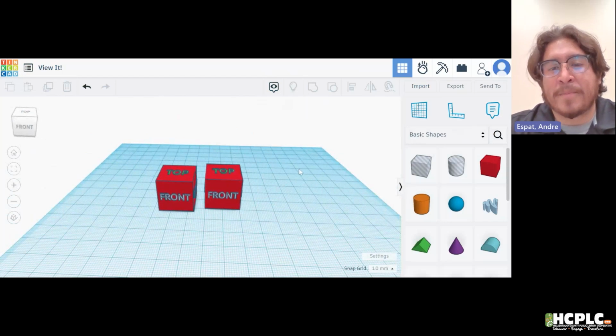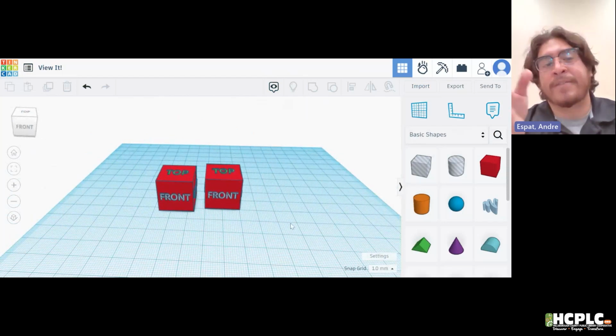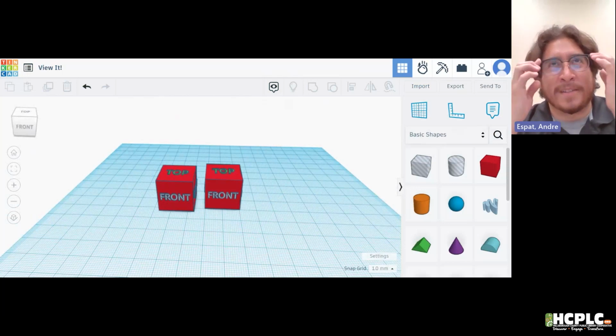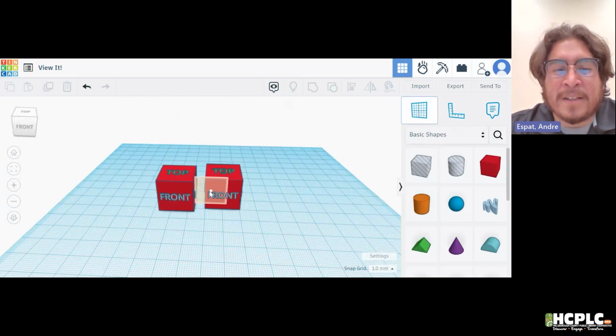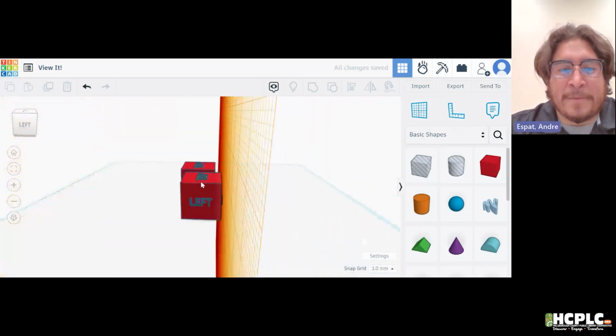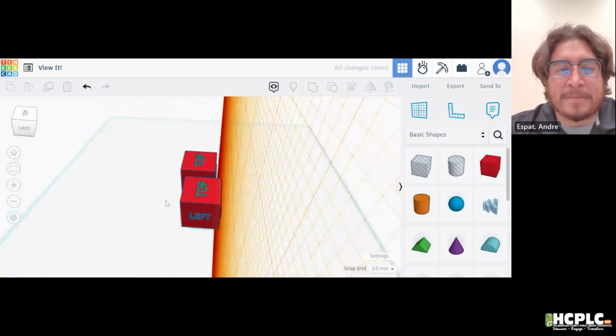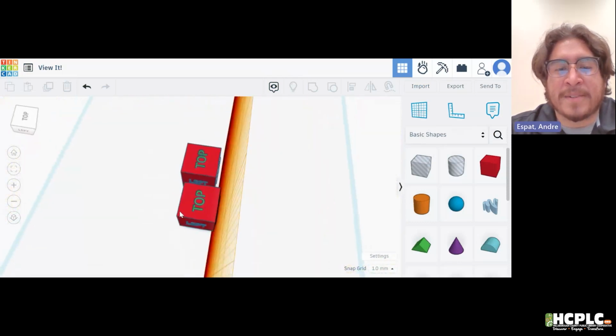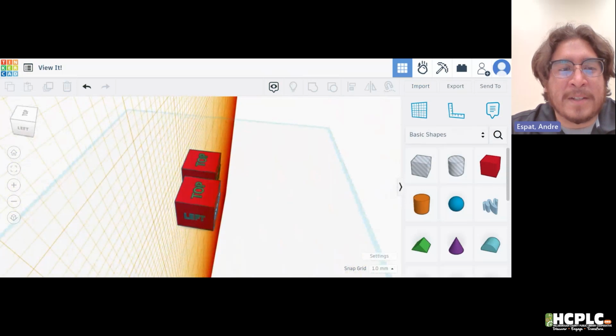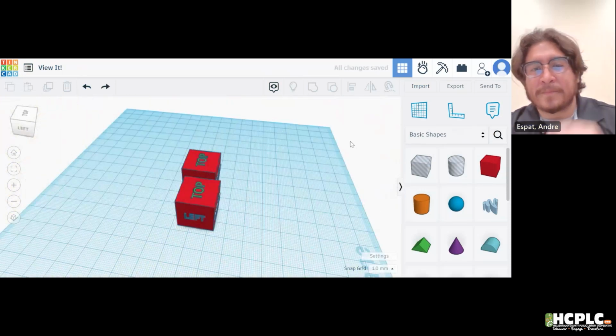You can put a separate work plane to run vertically so that you have an idea of where something is in relation to the rest of the build. Kind of hard to picture, but if you manipulate it, you can see where I want to place it. And now we have a different work plane that I can run anything next to and get an idea of how precise it is right next to it. Let's get rid of that guy.